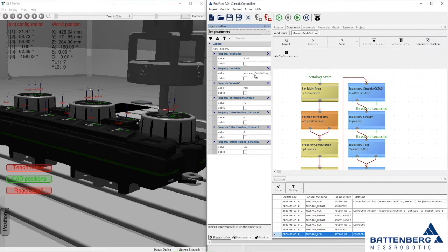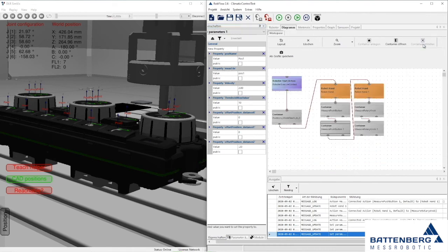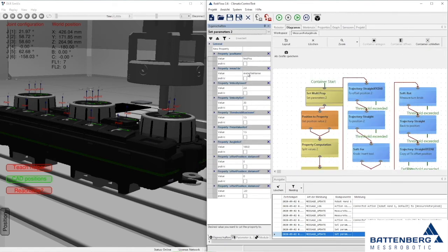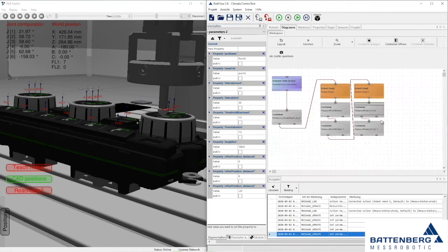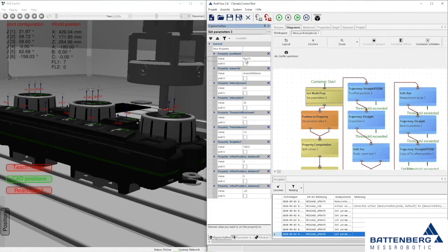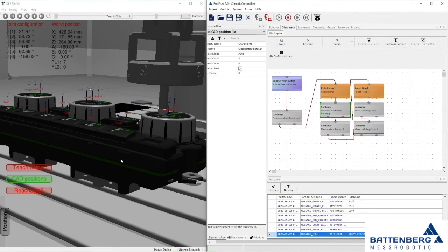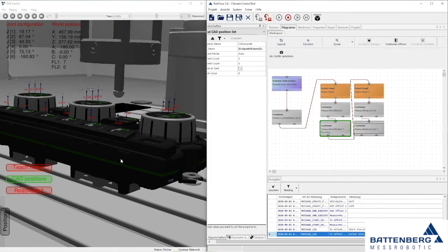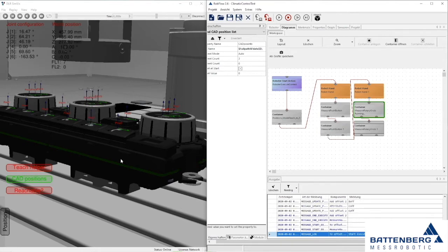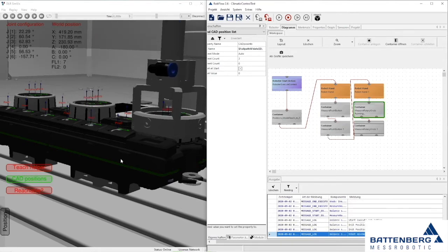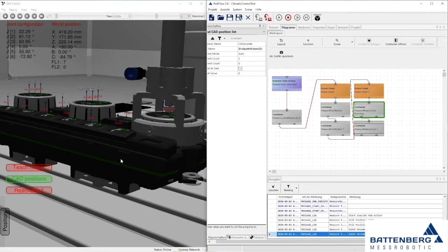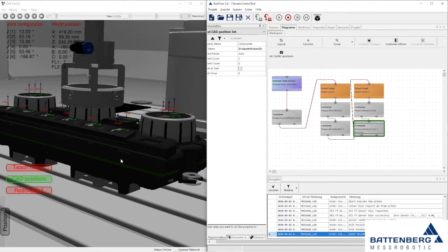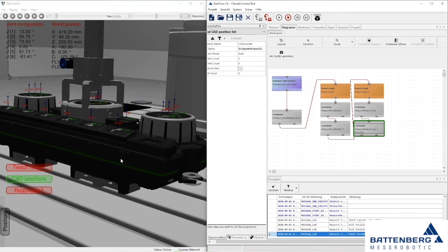Now program your RobFlow test sequences as usual. Drag and drop containers with the desired actions and measurement tasks onto the surface. Connect and parameterize them. You can assign the individual robot poses to the actions. You can simulate your test sequence at any time during programming. With RobFlow 2.6 offline, you can also program and simulate in the home office or in parallel to the occupied measurement robotics. Now the test sequence is to be transferred to the real measurement robotics.